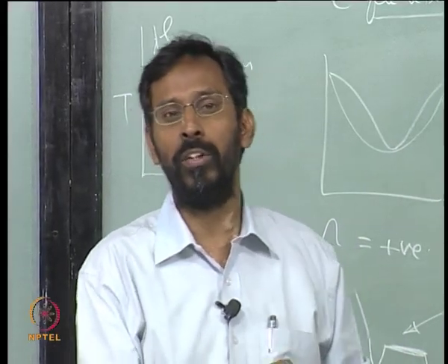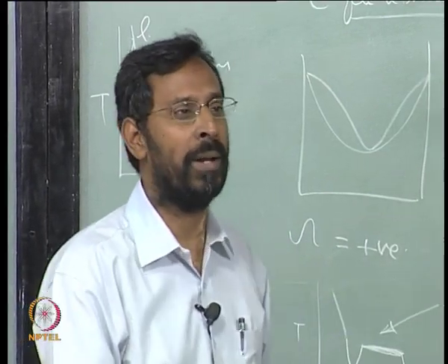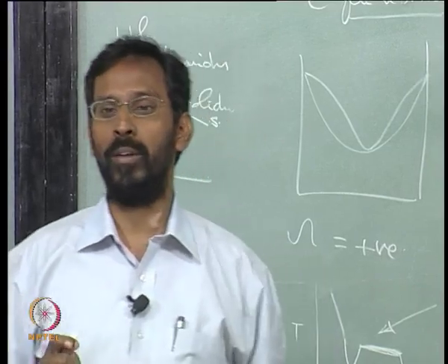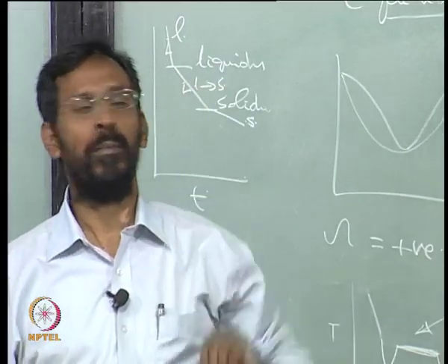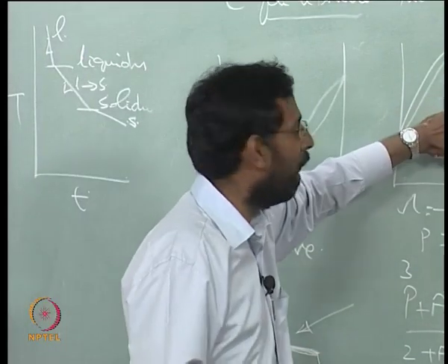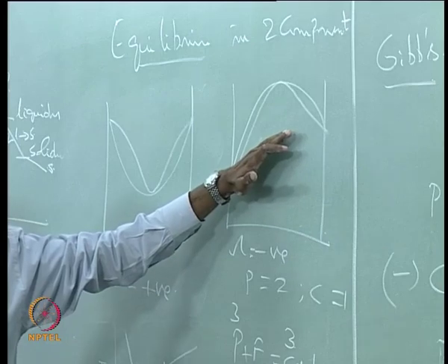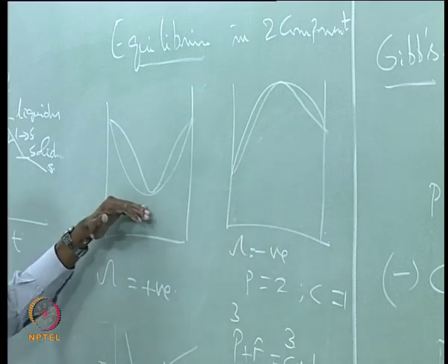In the copper gold system, Cu3Au, you will see something similar. In the nickel aluminum system, you suddenly see an intermetallic compound at the center of the phase diagram like that. So this is what is called a congruent melting system, whereas this is what is called a pseudo eutectic.